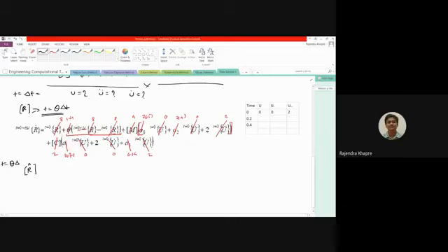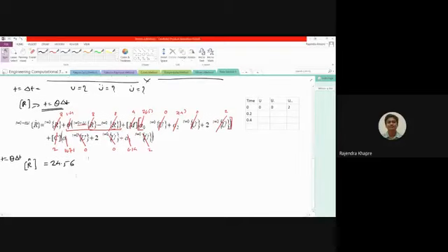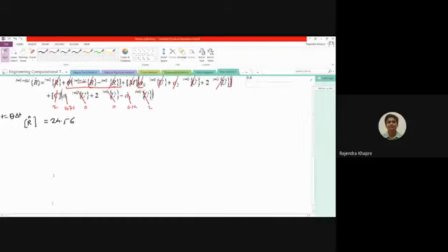If you solve this, that is the effective load vector at t equal to theta times delta t. Remember, this is theta times delta t. If you solve this, you are going to get a value something like 24.56. This is how you can get the value. Then lastly, once this value is known, you can generate the stiffness equation.